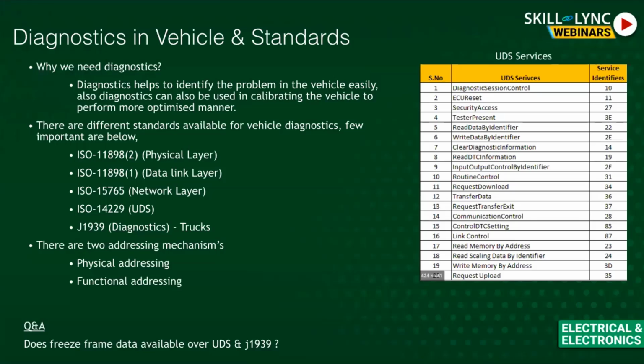You cannot just read the diagnostics by simply connecting some equipment. You need to send some commands, receive the messages and process them to know the information. To send the commands, there are some restrictions. There are different commands, right? I may need to only read the information, or I may need to reset a particular component to 0% or to a higher percentage, let us say 100%. So you can control different components using these UDS services.